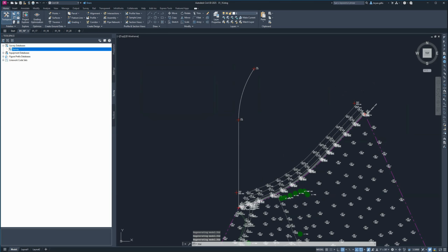Alright, so now what I want you to do is select the polyline that was created by that traverse editor. Then we're going to type E, enter, and that is going to delete it. Oh, it's got to be selected. So E activates the erase command, enter, now we see that line's gone.